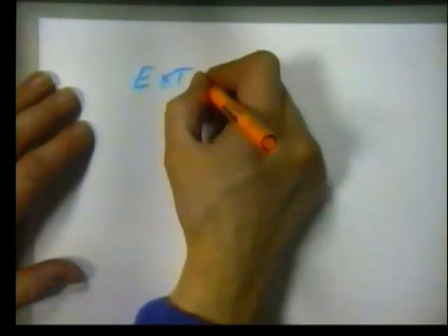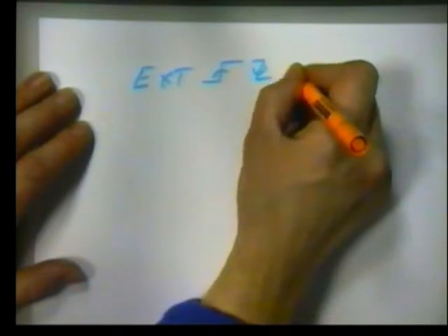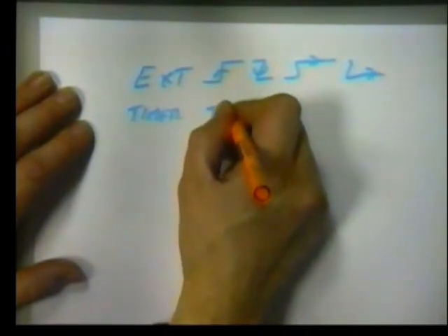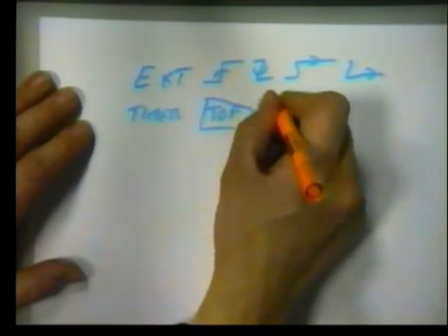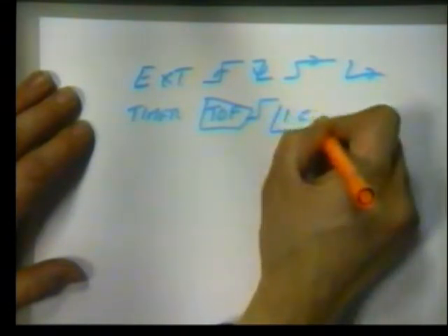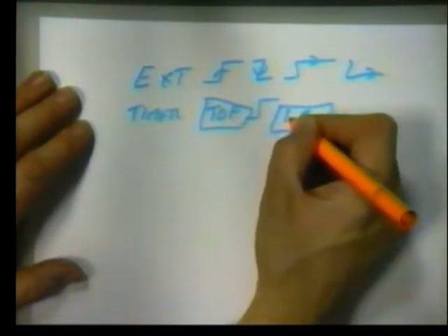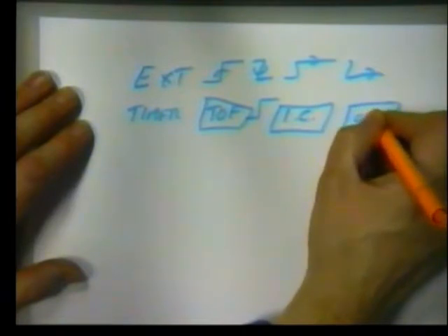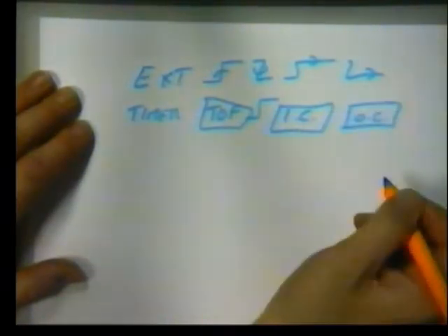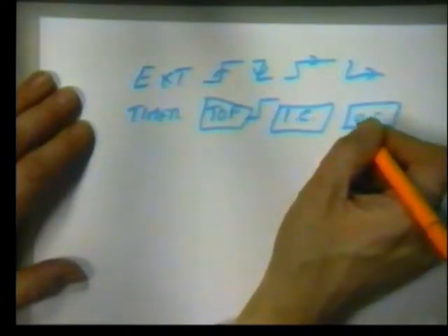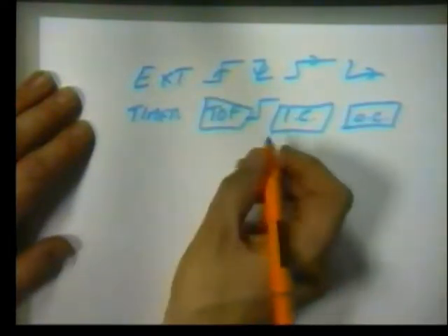We've talked about external interrupts: rising edge, falling edge, level sensitivity. Timer interrupts, that's timer overflow, where the counter has reached the end of its terminal count. We've talked about input capture, so we capture the actual time at which the external event occurred. We've talked about output capture. There are other parameters we could discuss here, such as the ability to auto-reload a count, the fact all these counters are memory mapped, but that's been discussed elsewhere. These are the tools available to us.